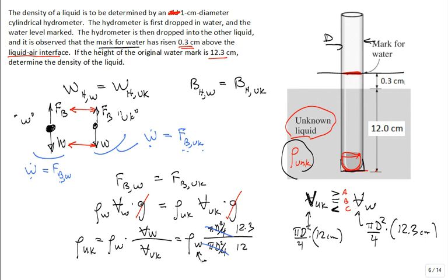And so what value do you think I want to put in there for water? 1,000. I know it's not perfectly 1,000. You've got to tell me the temperature, professor, because I know the density of water changes slightly. And oh, by the way, is it atmospheric pressure, 5 atm or 20 atm? You know, okay, yeah. But put in 1,000. There you go. So the density of the unknown fluid comes in at 1025 kilograms per meter cubed. The specific gravity of the fluid is 1.025. It's slightly more dense, true? Slightly more dense. Make sense?